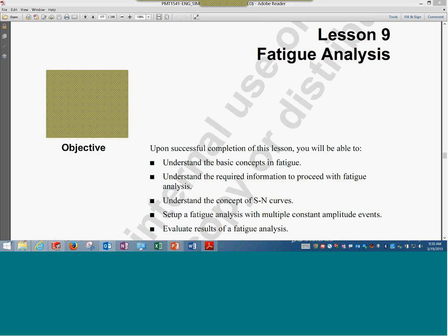We discussed buckling, which is one important thing. As discussed yesterday, in typical thin structures subjected to load, buckling can occur even at a lower force than what would cause yielding. So that is one. Two, third is fatigue, which we'll discuss now. What's the other important one? Resonance or vibrations, the natural frequency thing that we discussed yesterday.